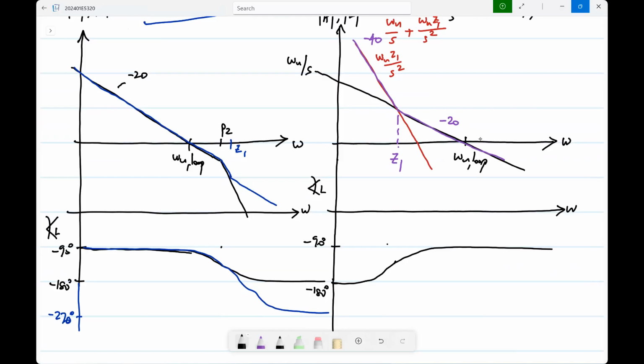So the point is, if this phase is between minus 90 and minus 180, the magnitude will have a minus 20 dB per decade roll off. Essentially, it will have a first order behavior. So you already know this. For a stable system with reasonable stability margin, at the unity loop gain frequency, the magnitude should cross unity at minus 20 dB per decade slope. That's the same as saying the Nyquist plot should cross it in the third quadrant.